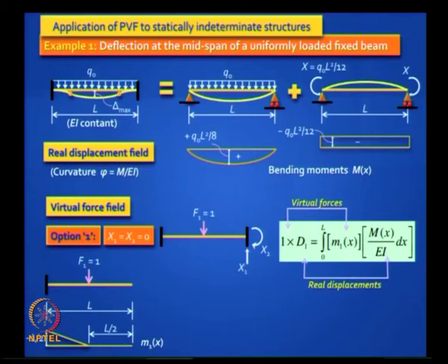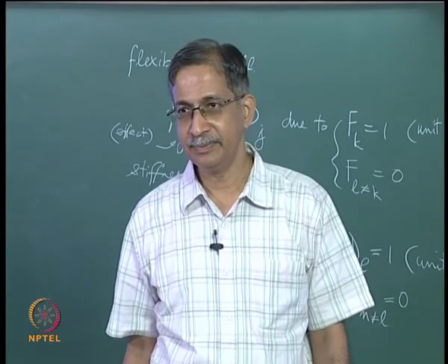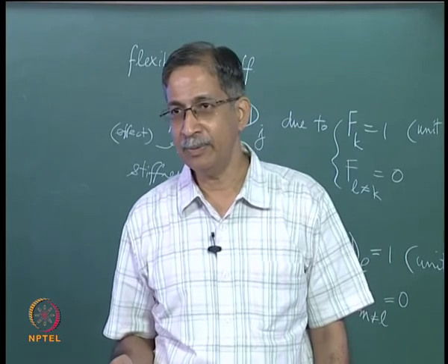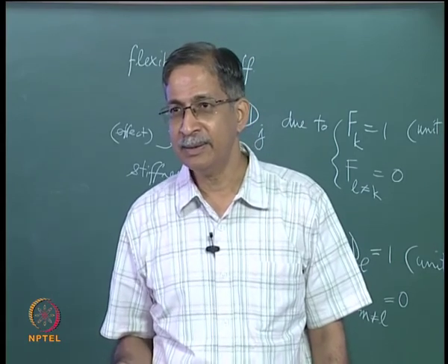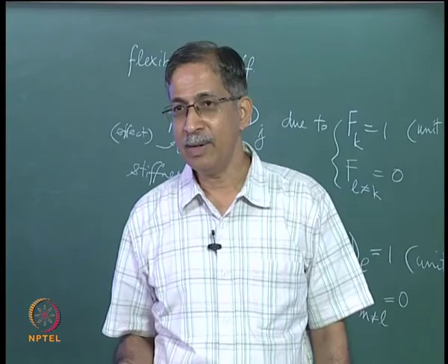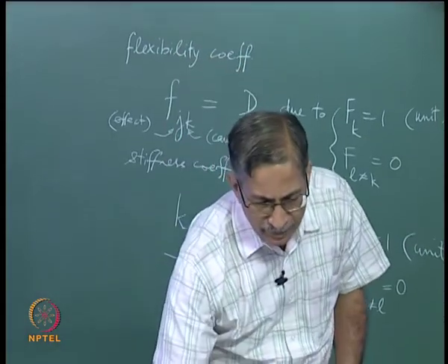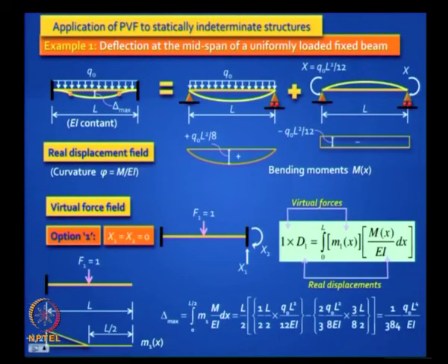Now will you try this out on your notebook? Can you get the deflection at the midspan? I will help you. Just check out this solution. You are multiplying this triangle with these two diagrams. One is a parabola and one is a rectangle.